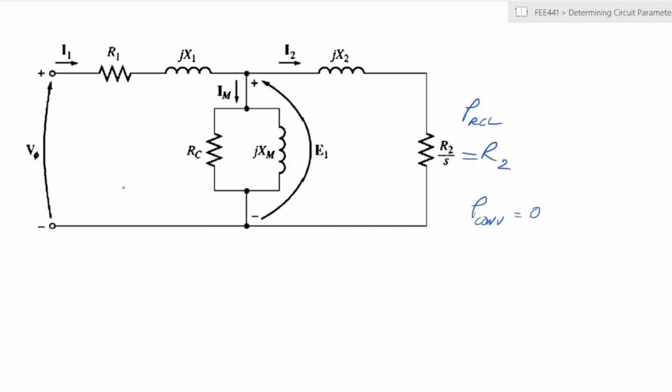It means that if we look at this particular arm, all the current that we are talking about will be flowing through X2 and R2. So more of the current will tend to flow in this side and less of it will flow through this arm, for the same reasons we talked about before. This value of R2, remember R2 is very small, different from what we saw before. So the reactance that is encountered by the current as it splits in here is very low. In this arm, the reactance and the impedance is very high. So the majority of the current will be flowing into I2.